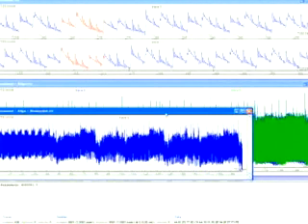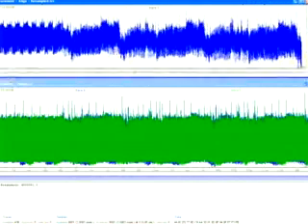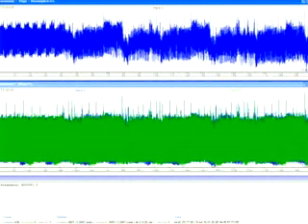Now, in this case that works. Of course, it may depend on the hardware: there may be a very special spot in that clock cycle that's very sensitive to the input data. Then you don't want to do this. You maybe just want to take that piece of the clock cycle. So it very much depends on the implementation. This is more or less the quick and dirty way. You just throw everything together.